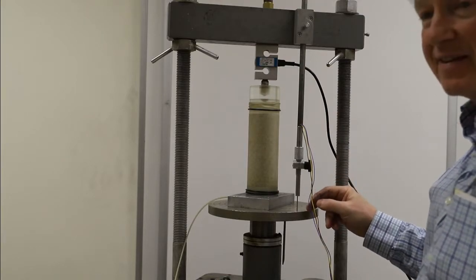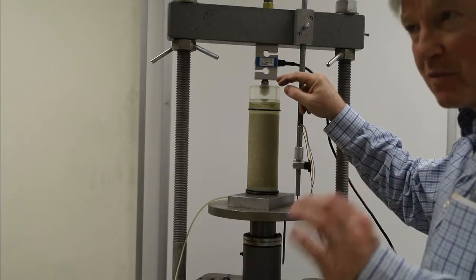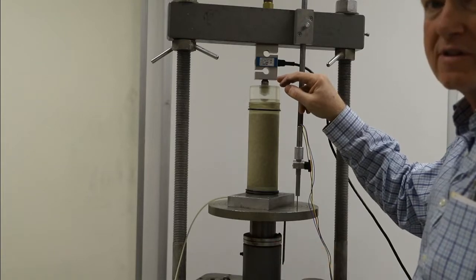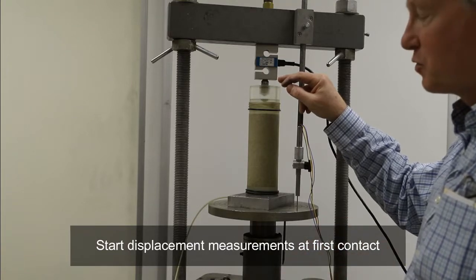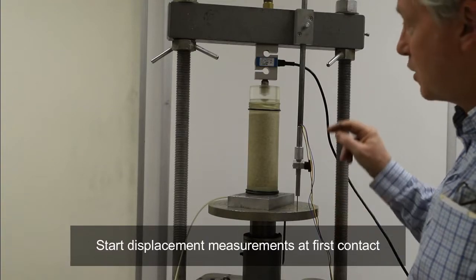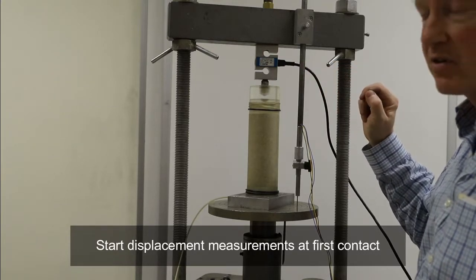So the LVDT value that represents zero strain is immediately before that contact, or at that contact when we first see load. So when you're looking at your data file, you don't want to start displacement measurements based on the beginning reading of the LVDT, because we don't even have contact yet, right? We want a good sense for what the zero reading is. That's why we do this.